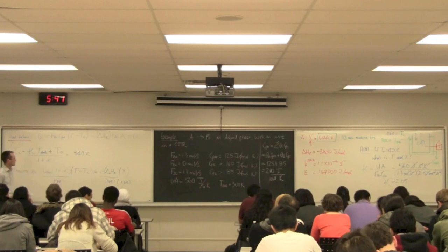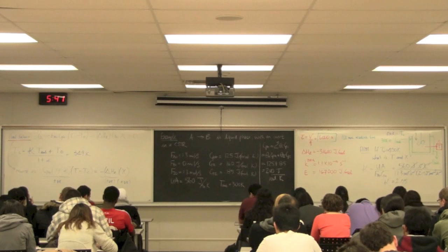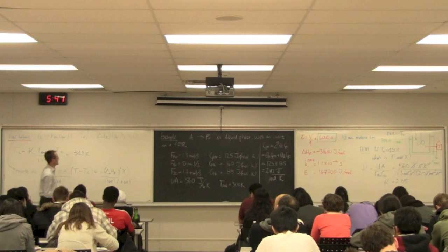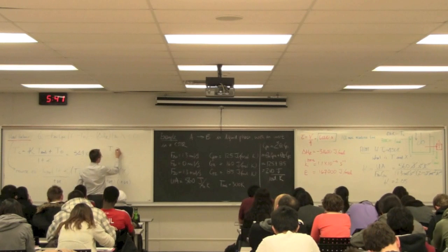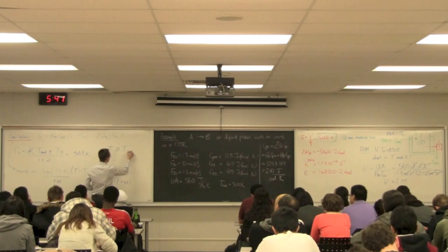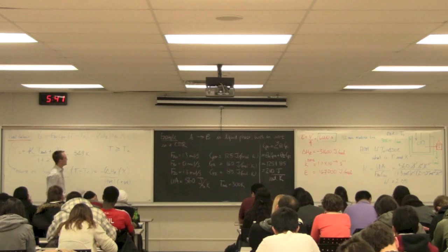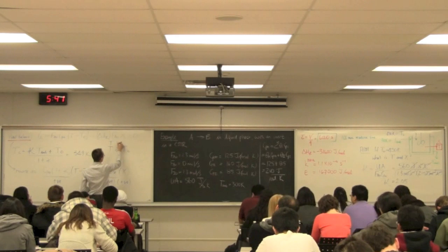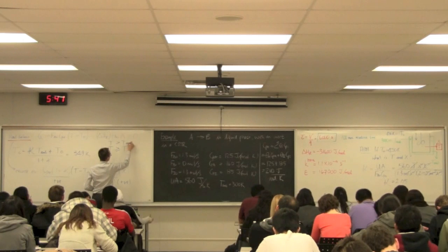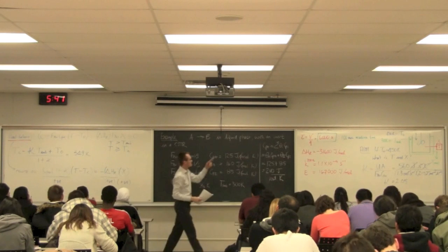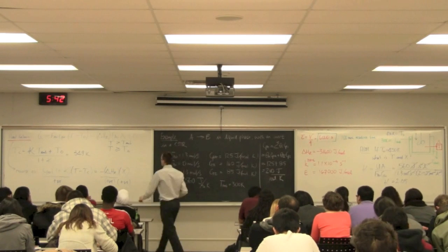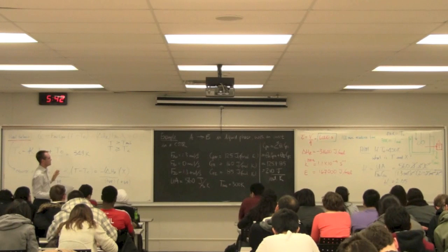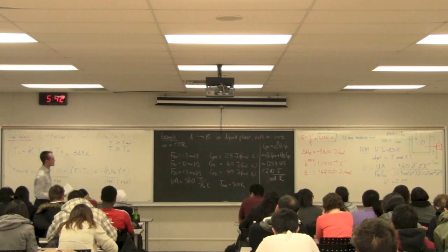So for that equation to hold, T must be greater than T_C. So that's a better estimate of T. We know that T must at least be equal to T_C. We also know, of course, that T must be greater than T_ambient for any heat transfer to take place. But T_ambient was 300 Kelvin, T_C is 341. So we can already eliminate quite a substantial region from our guess.